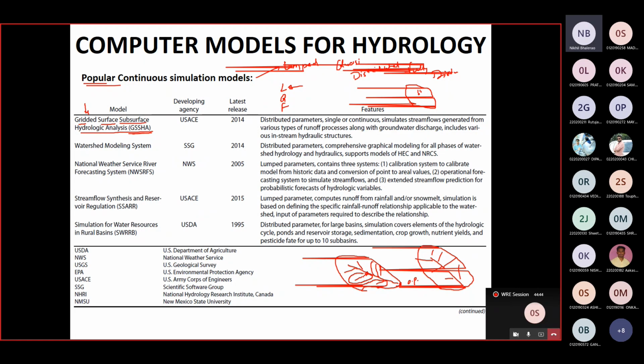Now why are we going to do this? Because if I go for smaller areas, the parameters I need to consider for this particular region will be restricted, meaning we are not distributing the same average value across the whole catchment area.